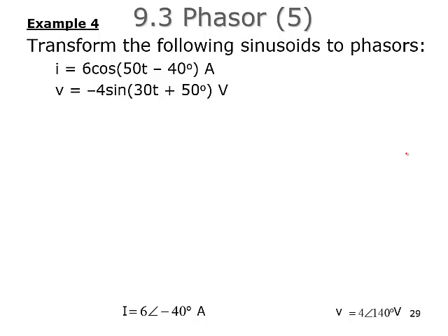Yeah. And basically the phasor transform, as a real brief recap, we use boldface capital I's to represent the phasor version of a time domain current, and you basically just strip off the magnitude and the phase angle and say, that's a phasor. And that represents our current in a timeless domain. There is no time in phasors. It's just this constant number.